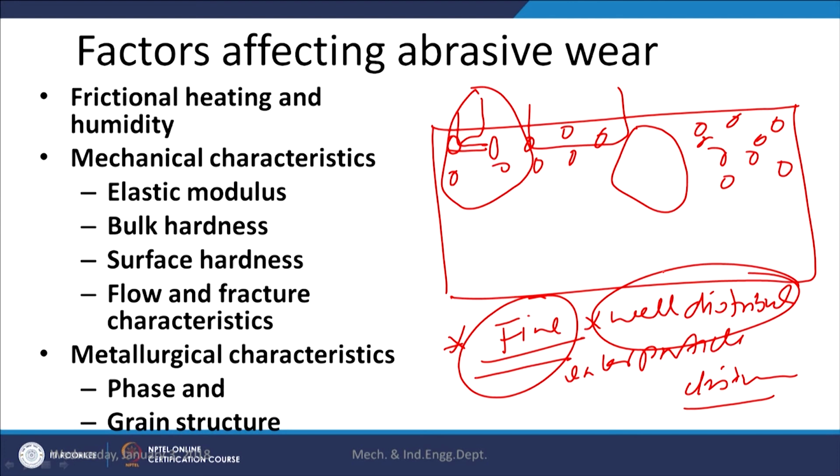So, considering the service, the type and size of abrasive must be considered for designing the surfaces, so that we can have constituents of the suitable kind and suitable size at the surface layer, so that it can offer the required abrasive wear resistance.